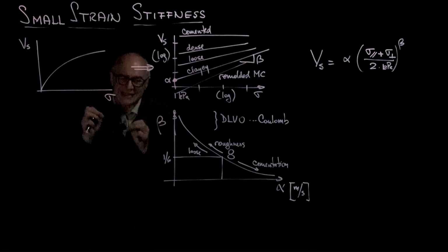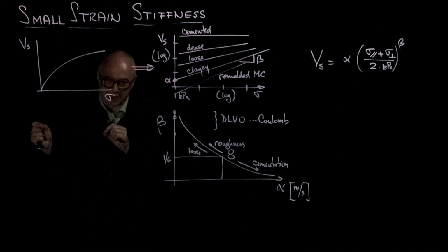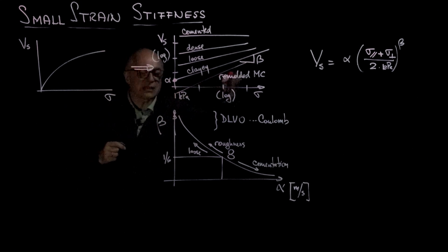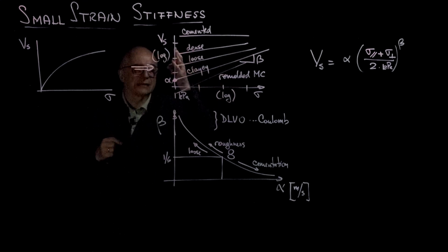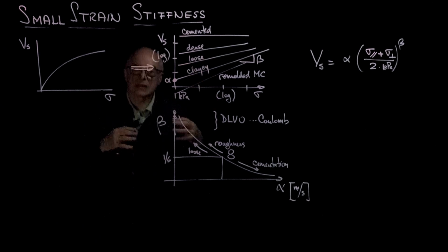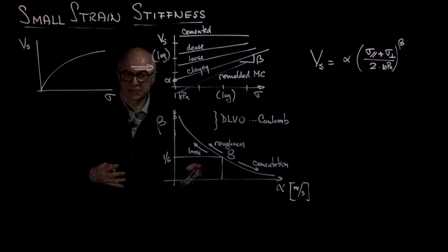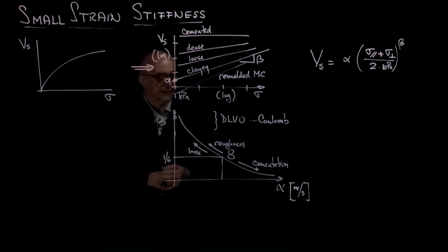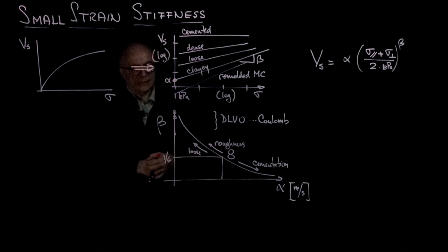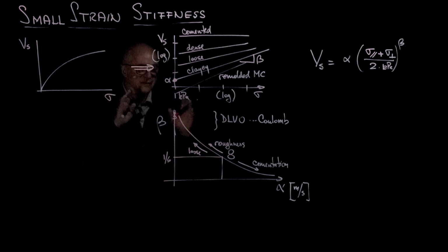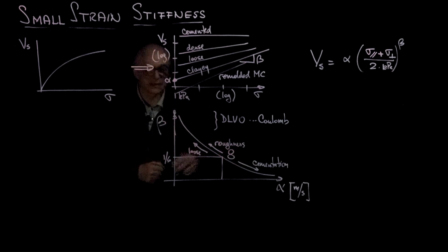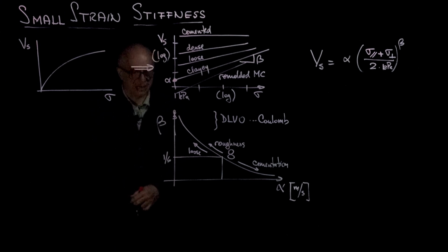So while the measurement itself is a small strain, what I'm checking here is the evolution of a small strain stiffness in a soil that may actually be experiencing larger strains and fabric changes. At the end of this presentation, you will see a slide that contains a very large data compilation from around the world and the expression for this alpha-beta relationship.